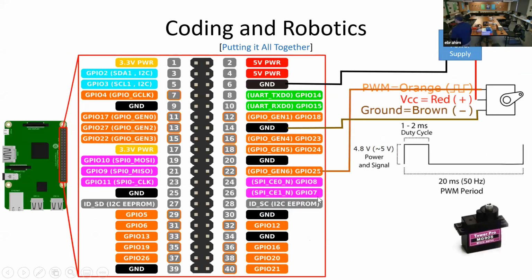So we understood how the servo motor works. Now what we have to understand is from the Raspberry Pi point. As I initially pointed out to you in the diagram, there is a connector over here. This connector is a GPIO connector, which is a general purpose input-output connector. On that connector, we have to connect this motor.